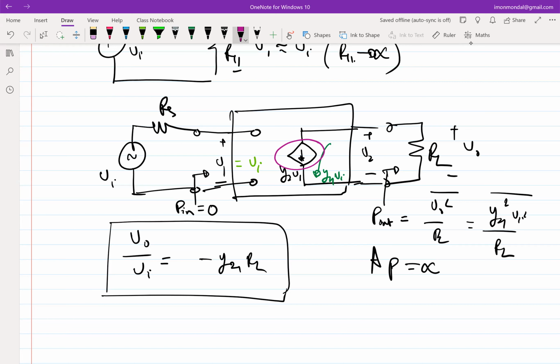So essentially, an IV characteristic of a device has to exist in order to get Y21, right? So you cannot say that I'll bias the device at 0, 0, no V, no I, and get Y21. You'll get 0 Y21 also. So it essentially means that in order to get some decent Y21, you have to burn some power in the device.